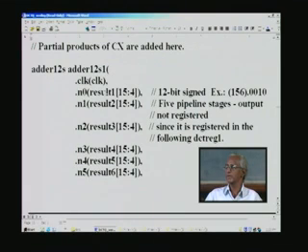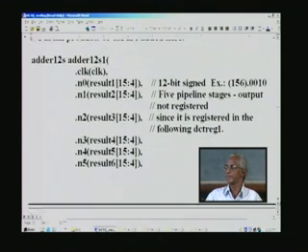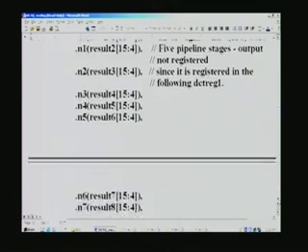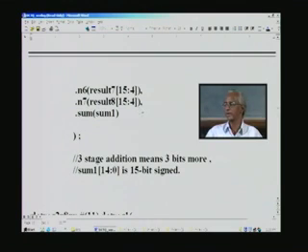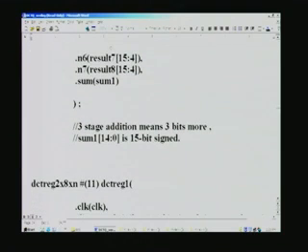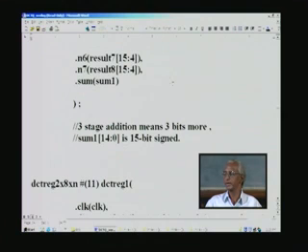This is not registered because we are going to register with the next module that we are going to look at, that is called the DCT-reg, and up to N7 you have here. Note that we have dropped 4 bits here because we do not need that higher precision. These precisions have been arrived at after a few iterations, keeping in mind the quality of the image that we create. We have a very high precision computation of the same DCT-Q and reconstruction in MATLAB, and that serves as the standard reference for the computation of the quality.